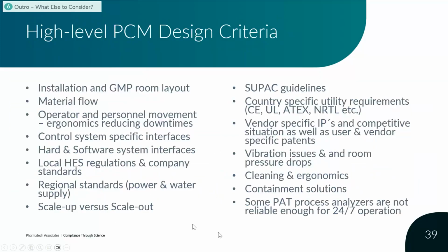Then another criteria, high level, I want to give you on the way. By the way, we have seminars and training seminars for each of these unit operations. I think we could spend another hour to talk about it, but there is of course more training available. But here just a couple of high level recommendations. Look at the material flow. Make sure that operator and personnel movement ergonomics is really considered in doing your layout work, because this reduces downtime. This is a high value asset, and there's nothing worse than having a high value asset sitting there waiting for cleaning and being complex in changing over, etc.